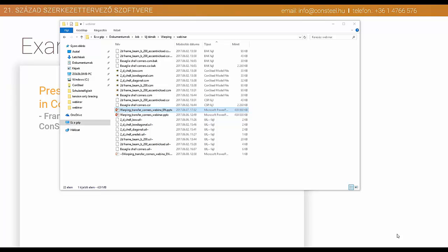So as you can see, this is a traditional frame. I used tapered columns and rafters. I used purlins as lateral supports, mainly on the upper flange, but at certain locations also at the bottom flange. And as you can see now, at the corner regions there are green types of colors. As I said, the definition requires a model portion to be made.